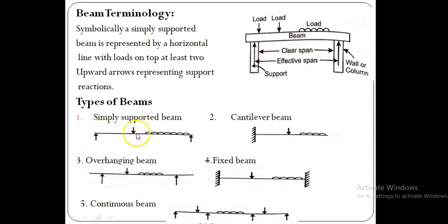Suppose we take this beam, it is subjected only to vertical forces, and therefore these two supports have vertical reactions at its ends. Okay, vertical reactions, and at its two ends there is no deflection, but it allows the rotation. So this is the property of hinged supports. Okay, it allows the rotation. So this beam may bend like this. This beam may bend like this.